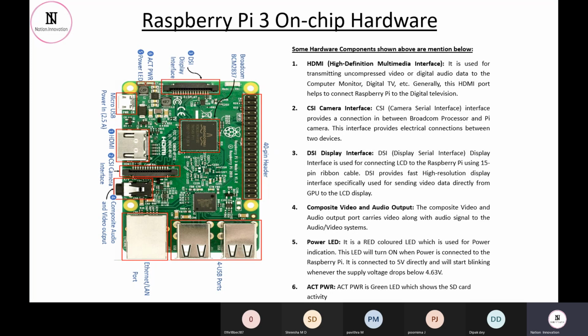The second biggest issue with the Raspberry Pi boards is that we just have digital pins to be interfaced. We do not have the availability to interface an analog input pin. In the Arduino, we have analog input pins, so we can take input from sensors as an analog value, but we are not able to generate an analog signal like a sine wave type signal.